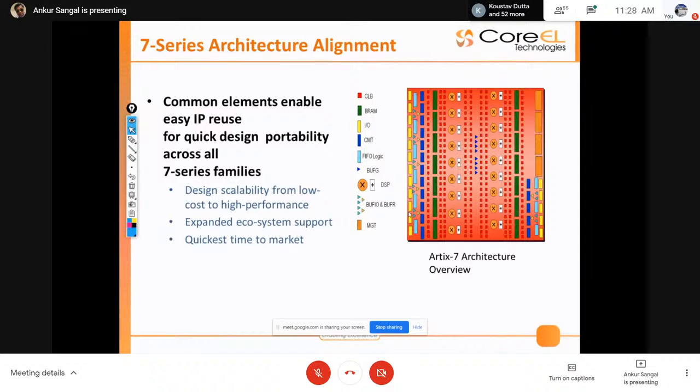And in your critical ICs, MGT pins are more, but for the normal industry or home automation industry, they mostly use HR pins, high range pins, because applications work at less than 2 Gbps speed. Okay, so this is the information related to input and output.